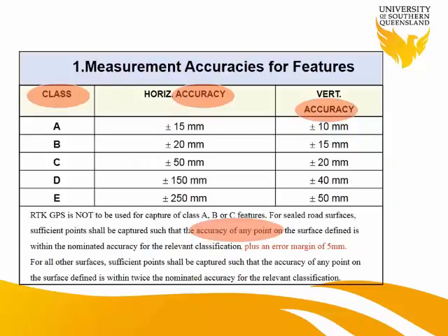What makes sense, again here you can see, is the old-fashioned one, where we used to have different classes of accuracy we could achieve, given as a horizontal accuracy and a vertical accuracy. Again, what does it mean by accuracy here? Is it standard deviation? It's the more traditional approach of surveying. So, okay, let's assume that accuracy is standard deviation, and precision, which is always confusing. But I will say, okay, this is sigma. But if it's sigma, is it sigma or is it 2 sigma? Is it 68% or is it 95%? So which one is this one? I'm not sure, and they are hugely different from each other.